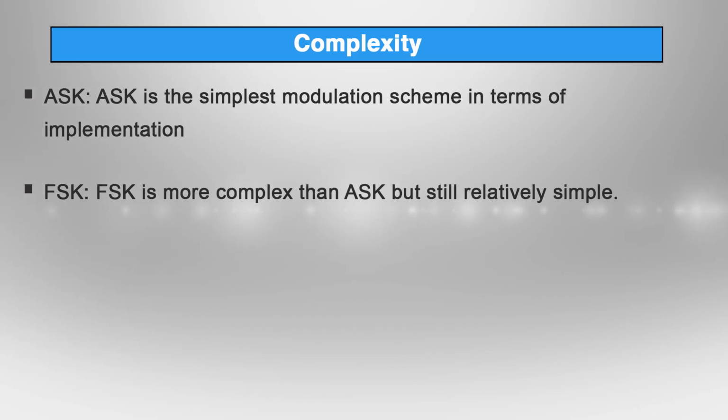Phase shift keying complexity. PSK requires sophisticated signal processing for phase detection and demodulation. Higher order PSK techniques introduce additional complexity in terms of phase tracking and synchronization. PSK is used in advanced communication systems where the benefits of its complexity, such as improved noise immunity and bandwidth efficiency,